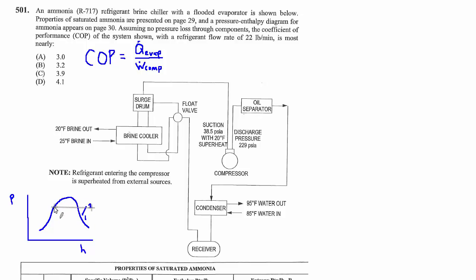And then we have a constant pressure process by which the refrigerant condenses in the condenser. That gets us to state 3, which is a high pressure saturated liquid. And then we have this isenthalpic process by which the refrigerant expands. So that's a vertical line straight down. After that throttling process, we'll call that state 4. And then the refrigerant's ready to go through the evaporator and absorb Q in and get back to state 1, and around it goes. So we could say Q in is for the evaporator, W in is for the compressor, and Q out is for the condenser.